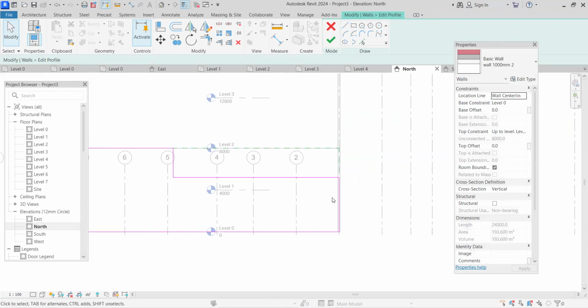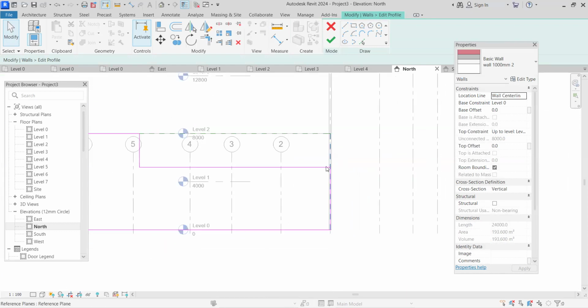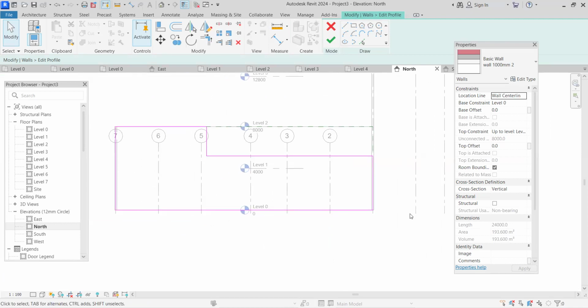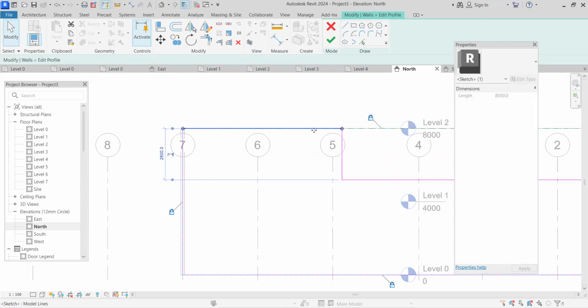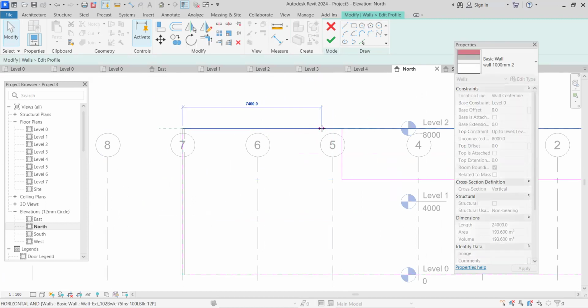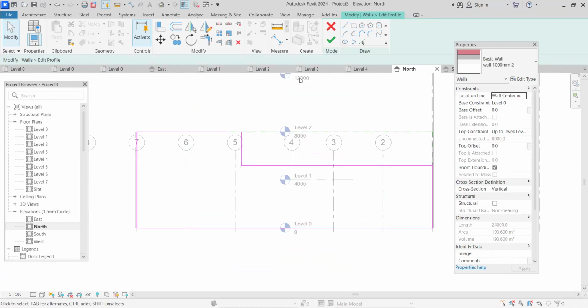So you make sure that that doesn't happen. So I make sure that there's no intersection here. All the edges are closed. Okay, it's also a very important thing to note. Let me just show you. So imagine if the edge was not closed, it was open like this, and then I try to finish in edit mode. So I click finish again here.